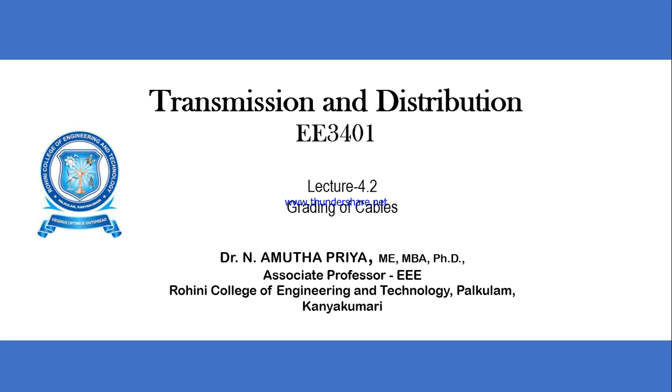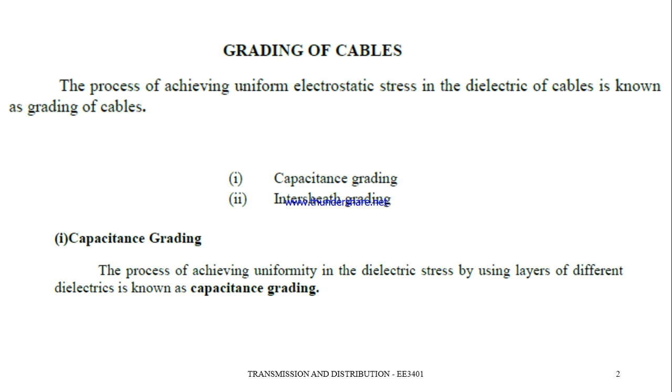We are discussing the transmission and distribution subject for Regulation 2021. Let us start with the grading of cables. What is grading? Grading is normally the process of achieving uniform electrostatic stress in the dielectric of cables.